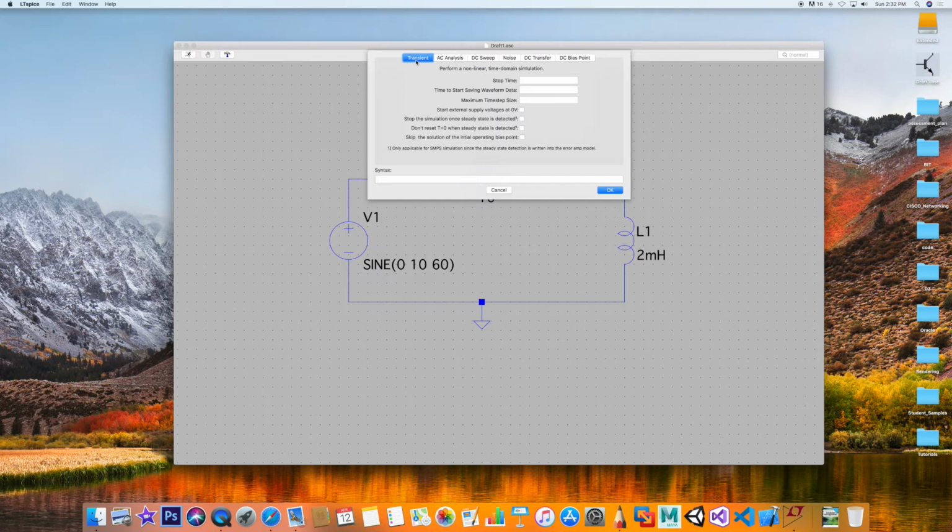In the transient, I'm going to simulate as if I'm using an oscilloscope to look at the circuit. In other words, I need to set my time division in a manner that allows me to see at least a full cycle of my signal. A couple cycles is good, 3. More than that, it gets busy. And you can't measure as accurately as seeing a full cycle.